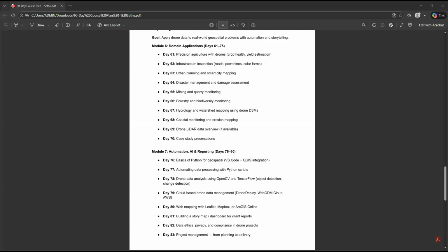Okay. So, what is this name called? Orthophotos, or orthomosaic, which we learned in Pix4D. Anything is fine. And what we have done with the GIS software, which I showed you, is some digitalizing work, some mapping work, and we also saw some volumetric analysis using the software itself. And we know how to create a database and how to work with it.